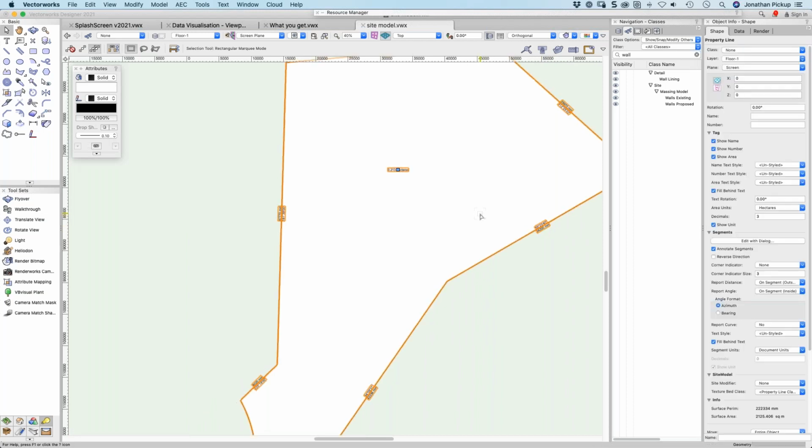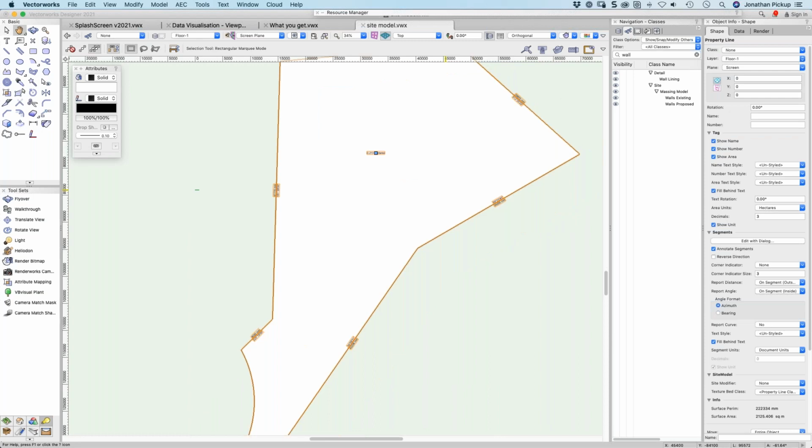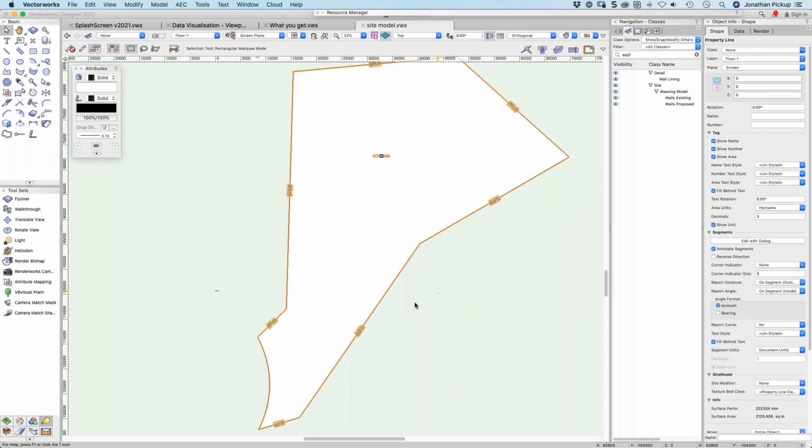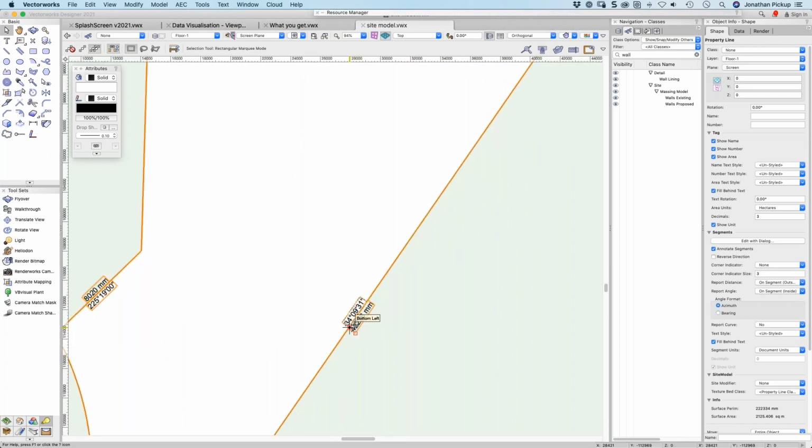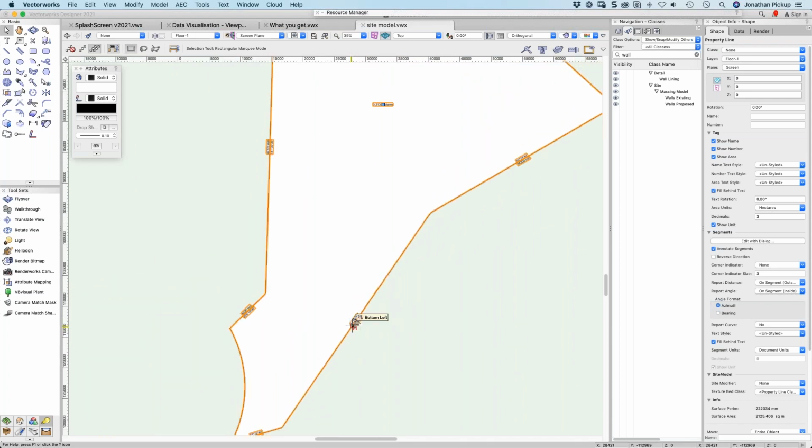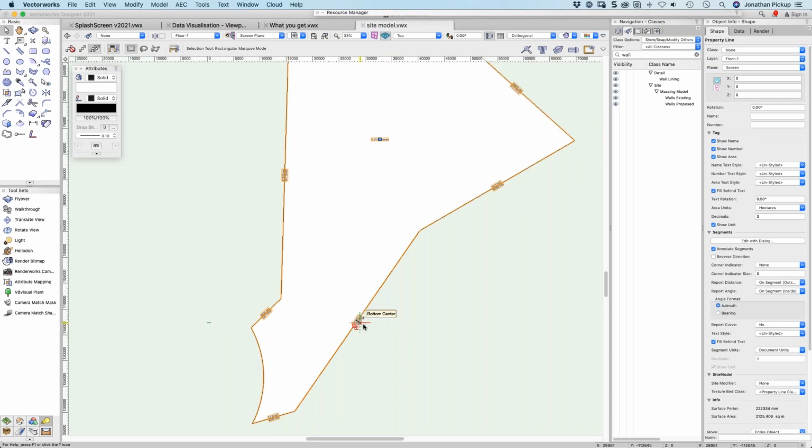Okay, so Jane, you do need better information. That one we had here just doesn't line up. It's a couple of meters short. That says 43 meters, the survey says 32. There's something a little bit strange. I don't know where the grid information is, and we're going to have to go back and find some good information. But if I've got a curve in it, I will tend to use the property line with a simple dialogue.